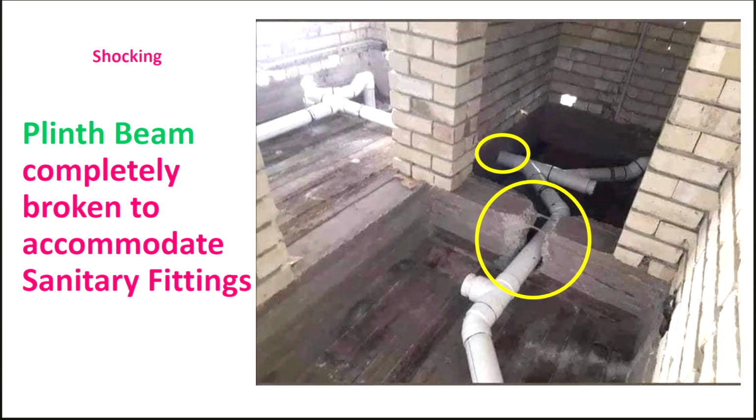At the time of planning itself, it should be catered where the pipe should go, where the sanitary pipe should go, and all these things should be designed at that time. That's why I was telling you that these things are required to be frozen in advance. Now, what is my remedy? In case I want to have this facility, then my structural designer will cater to this requirement.